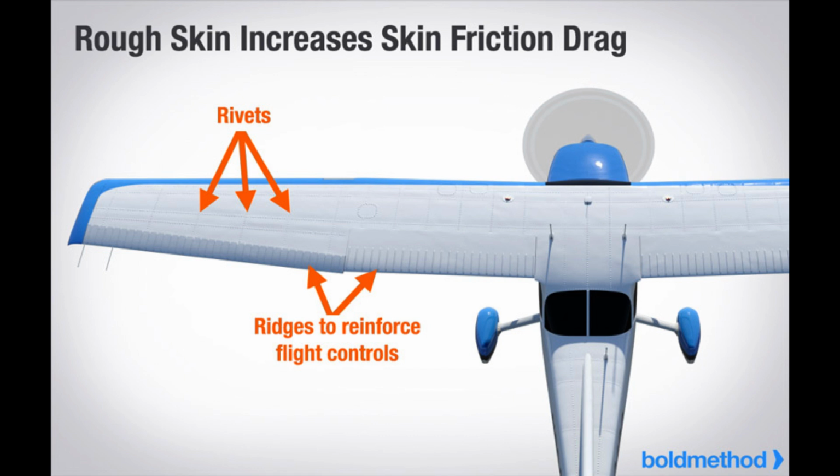In order to reduce the effect of skin friction drag, aircraft designers utilize flush mount rivets and remove any irregularities that may protrude above the wing surface. In addition, a smooth and glossy finish aids in transition of air across the surface of the wing. Since dirt on an aircraft disrupts the free flow of air and increases drag, keep the surfaces of an aircraft clean and waxed.